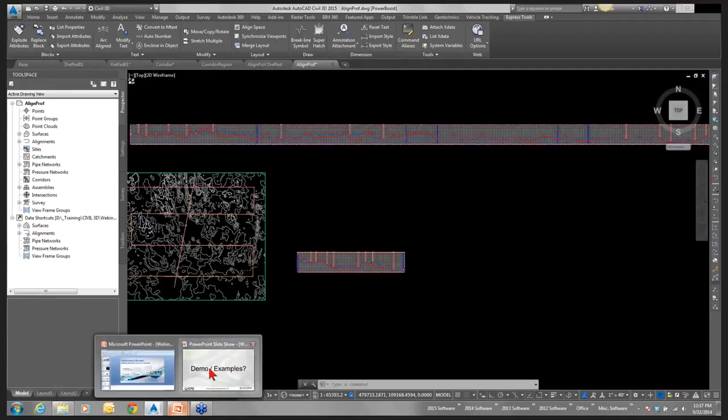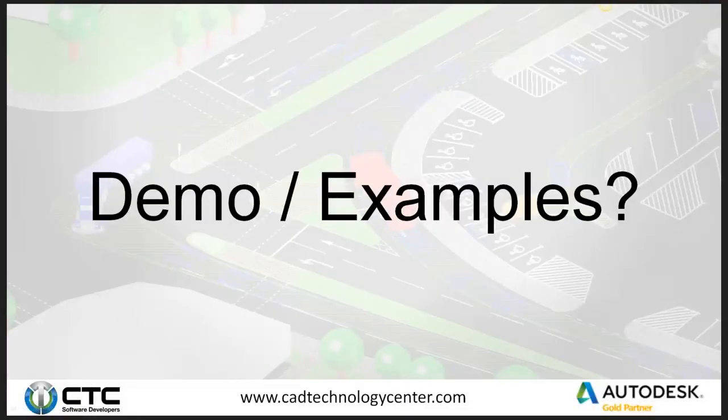So turn things off when you don't need them. Set your frequency lines to a higher frequency when you're not worrying about quantities. And then, again, turn things off. Set it to no display. Turn regions off. Possibly convert to a DEM model versus a tin surface.